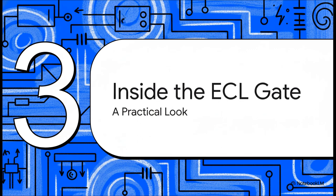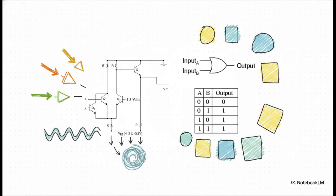Okay, so enough with the theory. Let's see how this stuff is actually put into practice. We're going to jump right into the circuits that make ECL tick. On the left, we've got a basic ECL OR gate circuit, and you can see its truth table right next to it. Now, the very first thing that should jump out at you is that negative supply voltage, VE. That's a classic hallmark of ECL. At its heart, this circuit is really a differential amplifier. You've got the input transistors Q1 and Q2, and they're basically being compared against a reference transistor Q3.